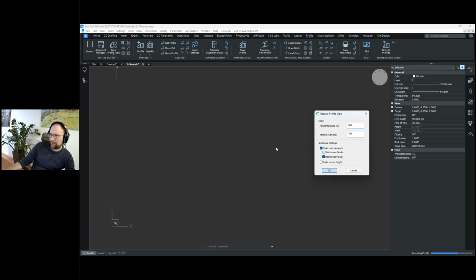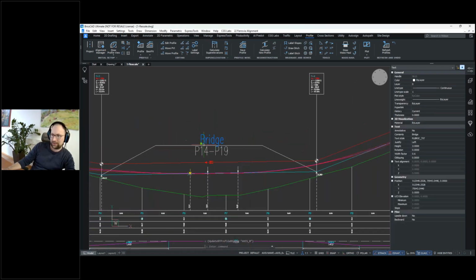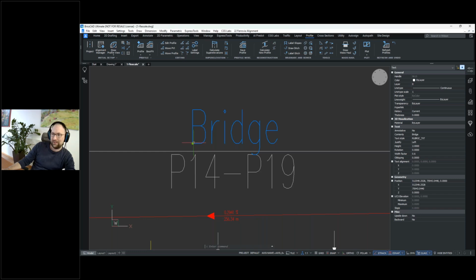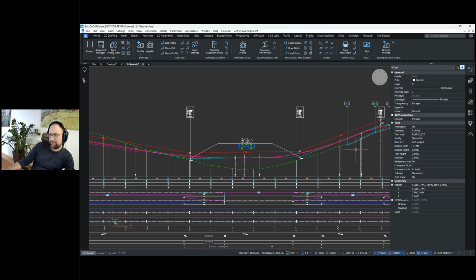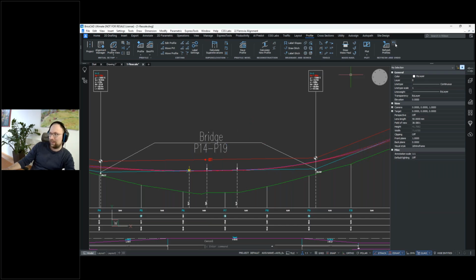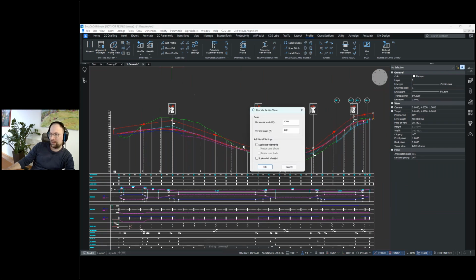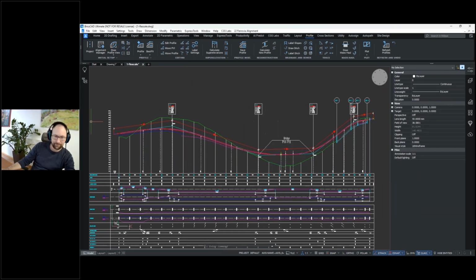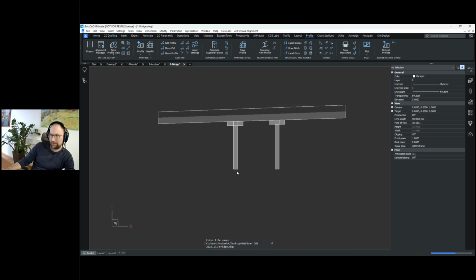And here you have to be careful that the user elements are always changed according to the insertion point. So here you can see that before it was 1 text height and now it's 2. Then it's the same thing with the user blocks. So let's see how this works. So I have 2 blocks prepared here that I will copy into my drawing.